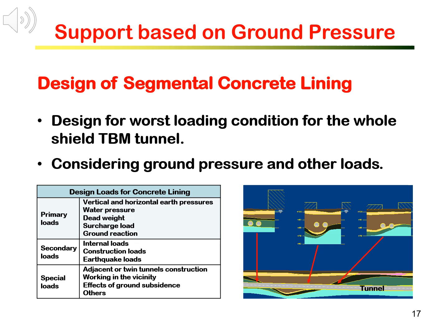Design loads to be considered for tunnel lining are shown in the table on the left. Sections of worst or most critical loading conditions are identified within the length of tunnel, as shown in the figure on the right. Loads are analyzed and considered in the design of concrete thickness, in terms of lining thickness and steel reinforcement.